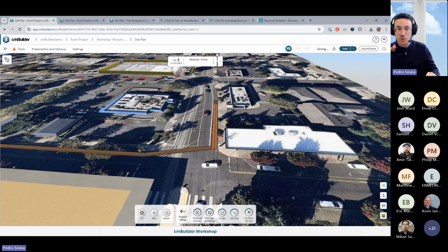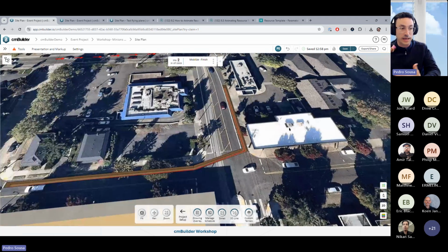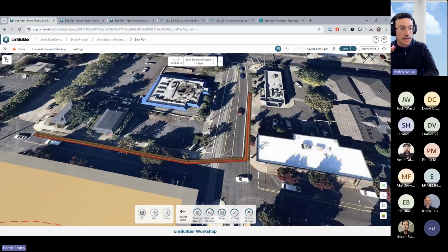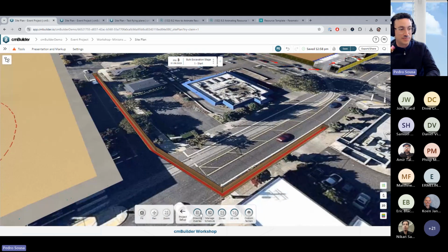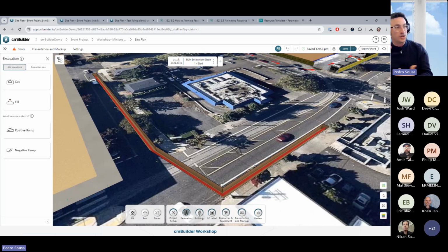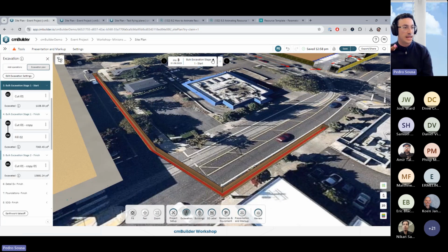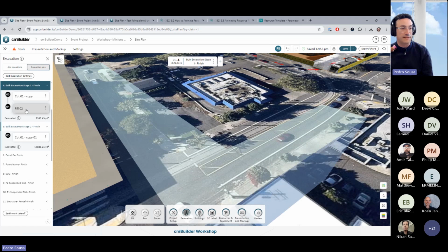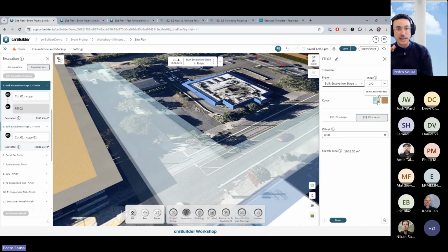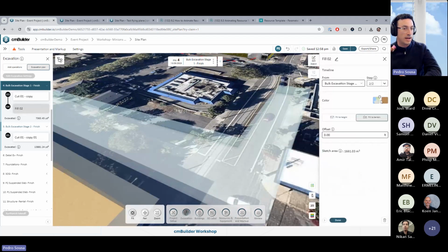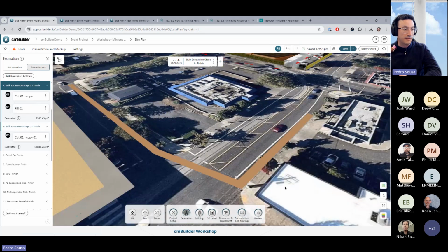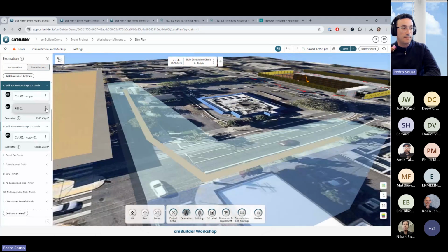Okay, so this is our 3D line usage for control of the pipes. And don't forget to create your backfill stage for this process, right? Whenever you're creating a trench, you can go over here in your excavation plan, and then you can create a fill that is a fill to terrain, and also it has the color of the top the same as the map. Okay, so this is a way for you to backfill this object. If I don't have the color, I can see that this backfill is going to look like dirt, right? So I can apply this backfill over here.